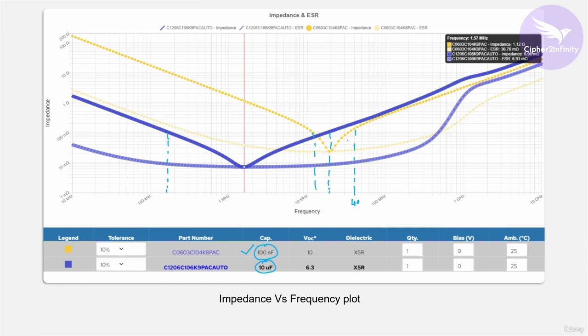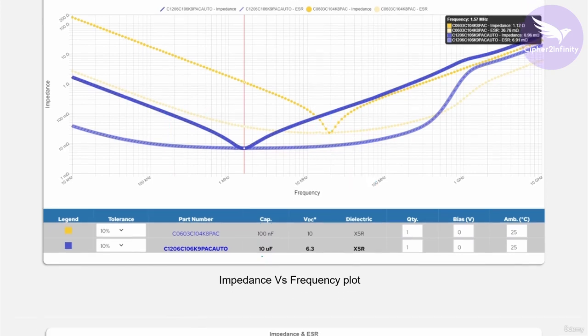We considered, so this one is actually going to be 200 or 150 milliohms. So let's consider 40 megahertz as well. So starting from 200 kilohertz till 40 megahertz, this range of frequencies you will be able to filter out when you connect two capacitors in parallel. I will show you the equivalent impedance versus frequency plot for these two capacitors now.